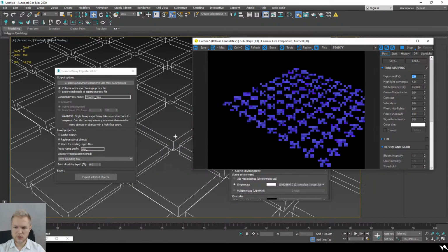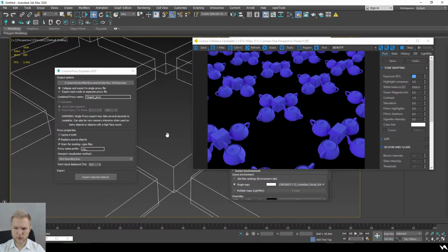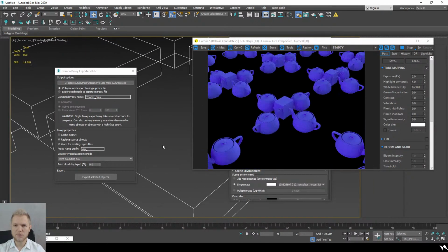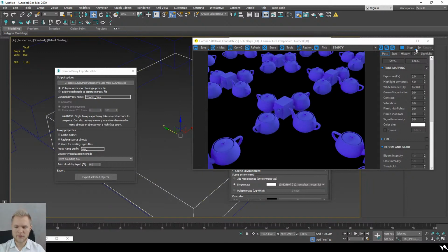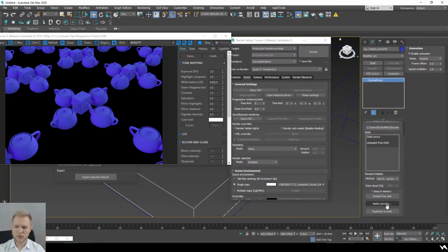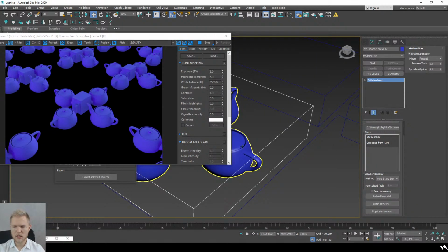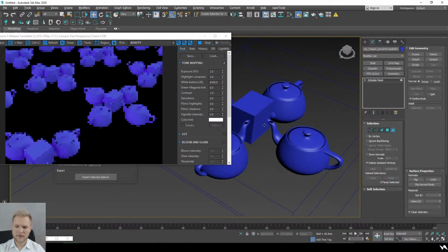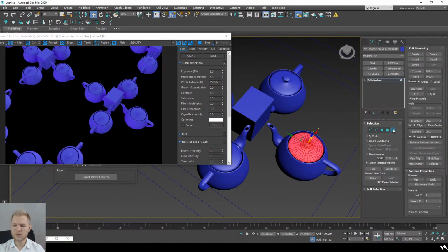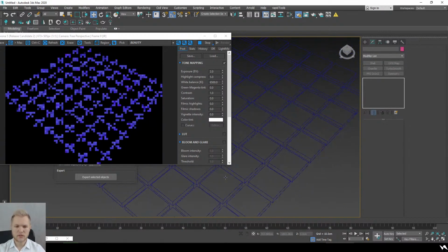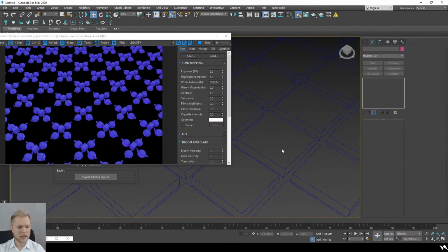Remember that it's best to first apply materials to your objects, because if you try to export something as a proxy before you add materials, you will have to go to the modify panel and reload this object as mesh. So, duplicate to mesh. Now it's going to be set to one object, and again you will have to add the materials now. So before you export your objects, remember to always add the materials. This is super important, so work on just one set.